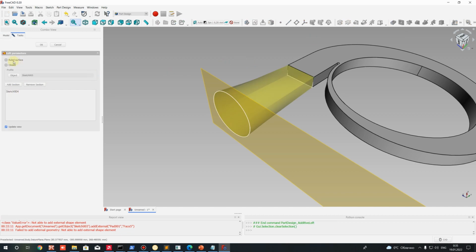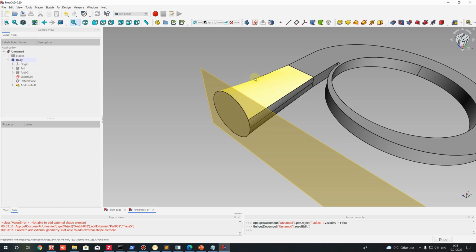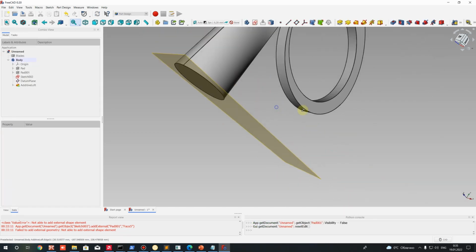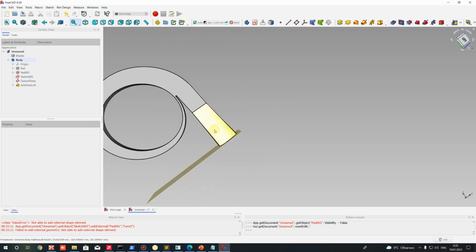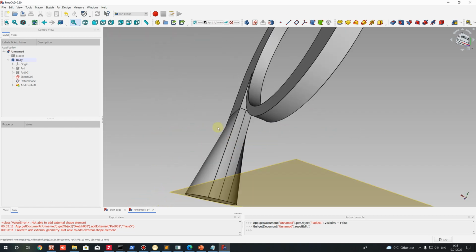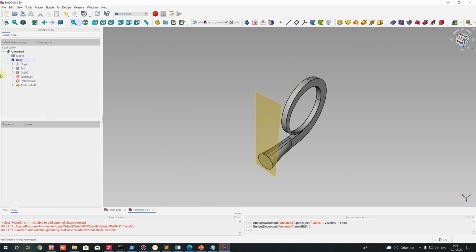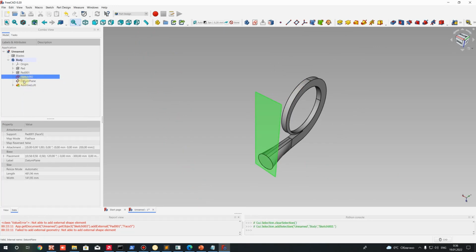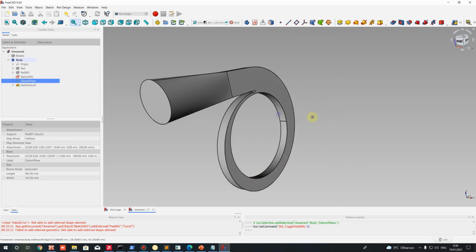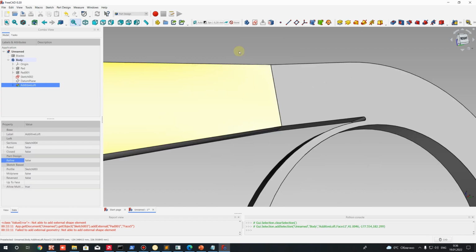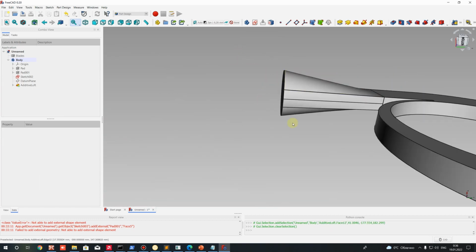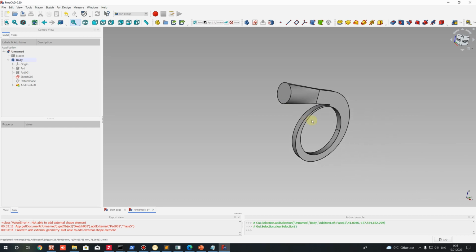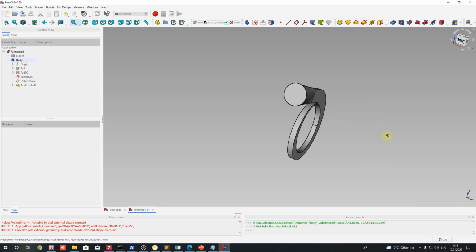Okay, just try click OK, and Part Design workbench creates a good shape of this. You can hide this, just choose it here and press space button on keyboard, and you will get a very high quality shape for your diffuser here.